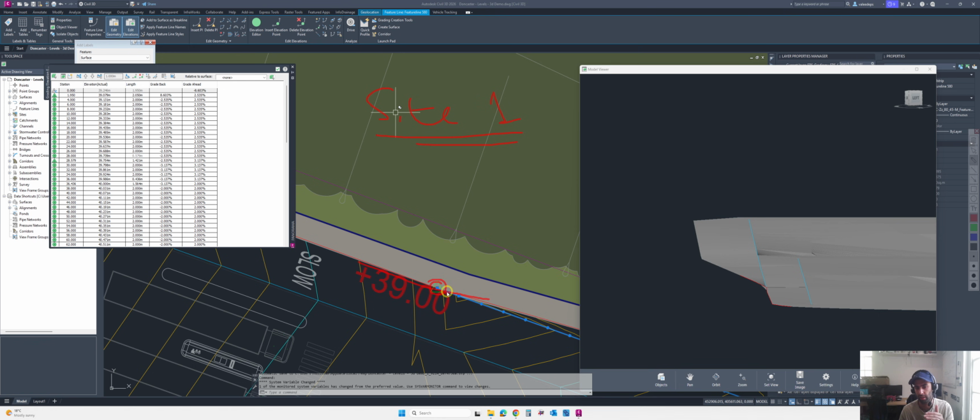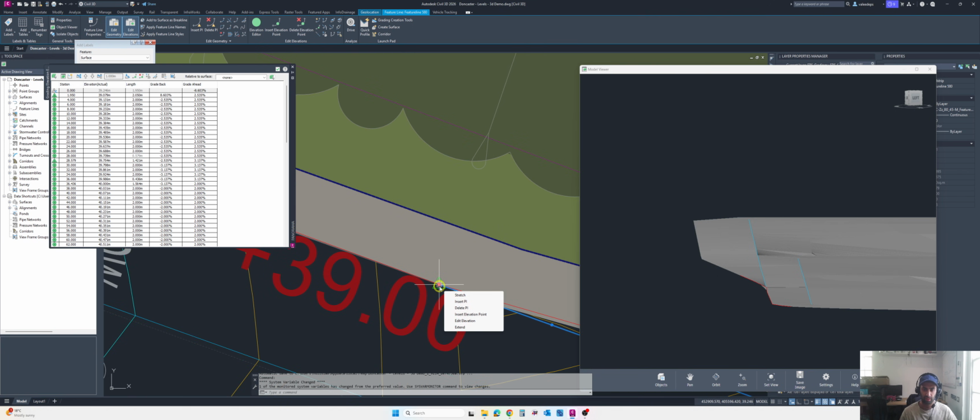For example, it's 39 and blue is 38, it comes all together. But if you have red line that has the elevation of, let's say, 39, and you have blue line that was at 40, but if you have changed that level, it will automatically change to the blue line. So it's all together. So you have to make sure that if you're working on a site to site, you keep the feature lines in one site. This will help you with dynamic changes so that you know that you are doing it properly. So both my feature lines are in same site. That's why I can't do it, because this is dependent on the red line.